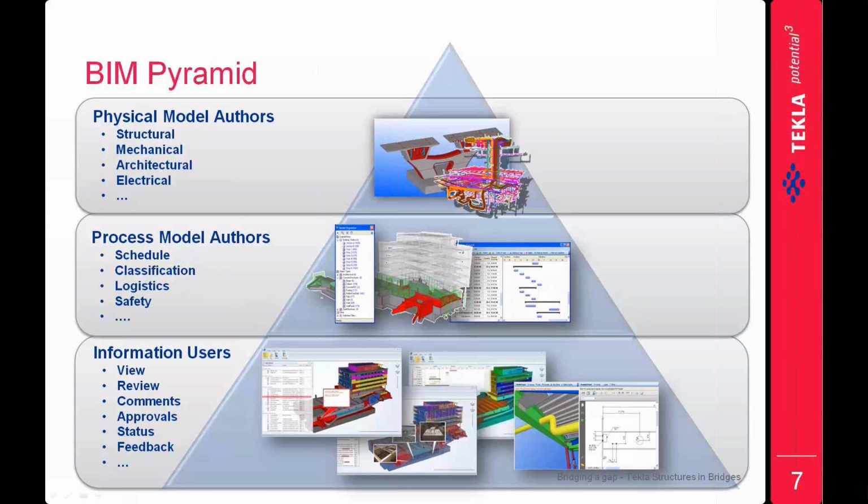In the BIM pyramid, the physical model authors, when you take any project, it's a mix of structural, mechanical, architectural and electrical, so many people are involved. Whatever model we create in the Tekla Structures environment can be transferred to the people who are checking this model. Even if they are not using Tekla Structures, we can share this model through Tekla BIMsight, where they can view the model, review the model, give their comments and give their approval. We can check the status and we can see the feedback also.